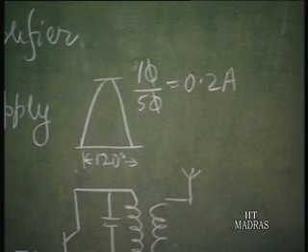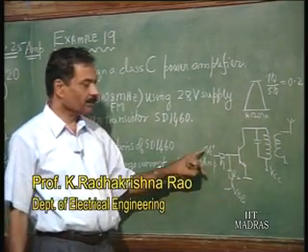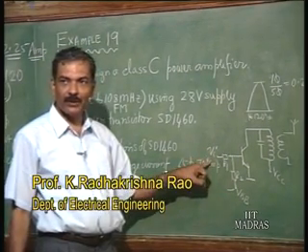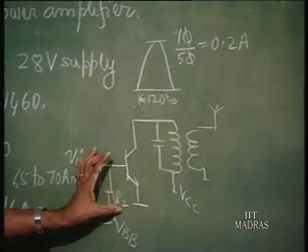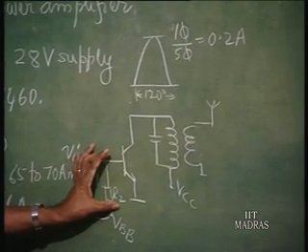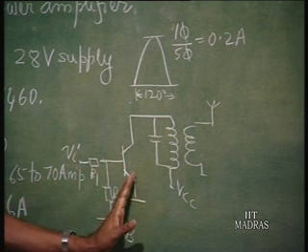That current waveform you have to generate using a specific value of VBB and a specific value of peak voltage here with a specific resistance. You have to assume that the transistor conducts for about say 1 volt. V gamma for all these power amplifiers you can typically take as 1 volt as against 0.6 or 0.7, because it is operating at fairly high current.